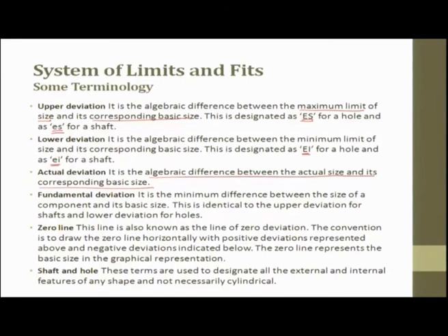Then we talk about fundamental deviation. It is the minimum difference between the size of a component and its basic size. This is identical to the upper deviation for a shaft and the lower deviation for a hole. So, this definition is also very important.